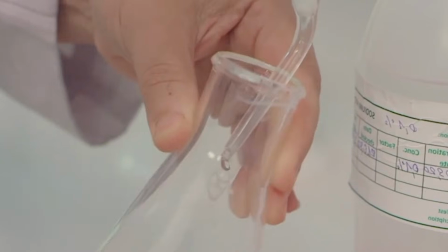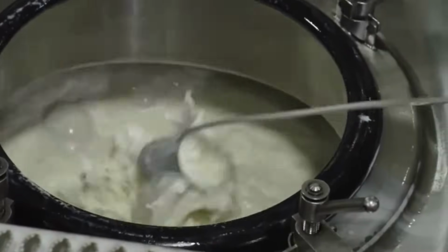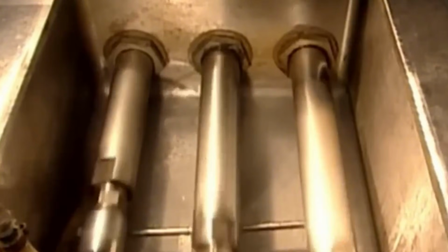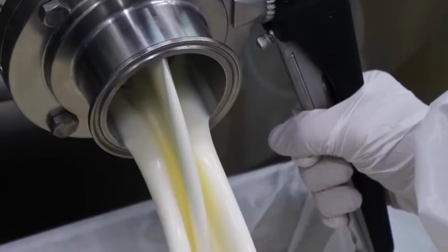Each pallet is wrapped using rotary stretch wrapping machines and moved into blast freezers or deep storage warehouses. Frozen storage areas maintain air temperatures between minus 25 and minus 30 degrees Celsius, with controlled airflow to preserve texture and prevent ice recrystallization. Each pallet is tagged with barcodes that link to a warehouse management system, allowing full traceability of production date, ingredient lots, shift information, and packaging batch.